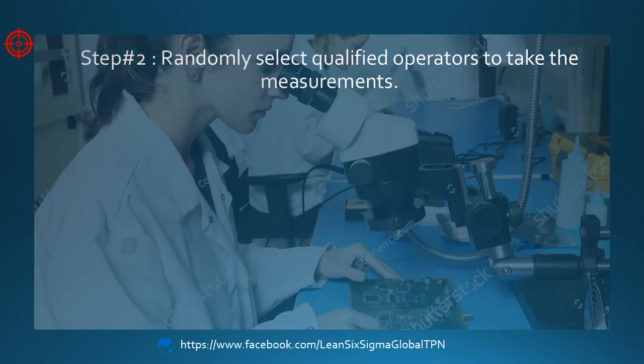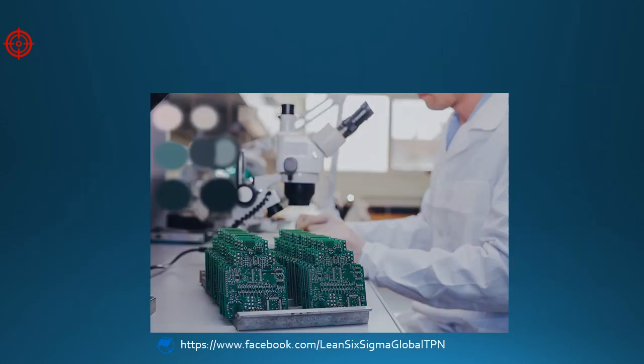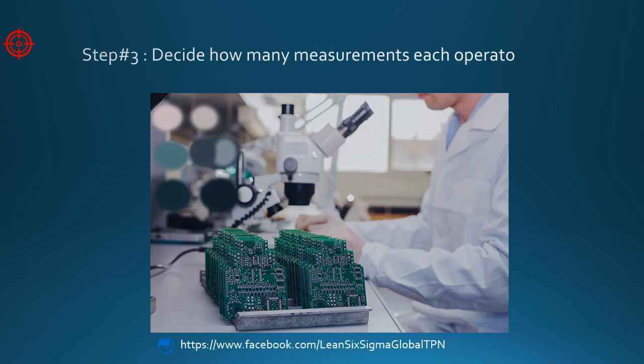Next, we randomly select qualified operators to take the measurements. At the PCBA Pro, we'll use 5 operators. Our next step is to decide how many measurements each operator should take. We'll take 4 measurements of each board per operator. But before we proceed, let's review some guidelines that the operators should follow while taking their measurements.